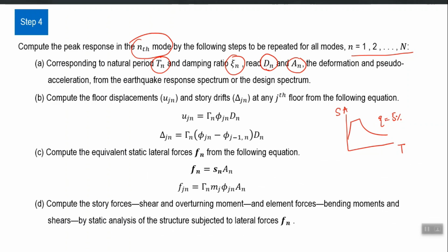If you want to plot it for 2%, the factor will be greater than 1. So there are several equations which provide you such a modification factor. They are called damping modification factors, to modify the spectrum height based on the damping, right. There are some building codes which directly provide the equation in their main provision, which is a function of damping ratio as well, so that you can directly plot the curve according to your own damping ratio.